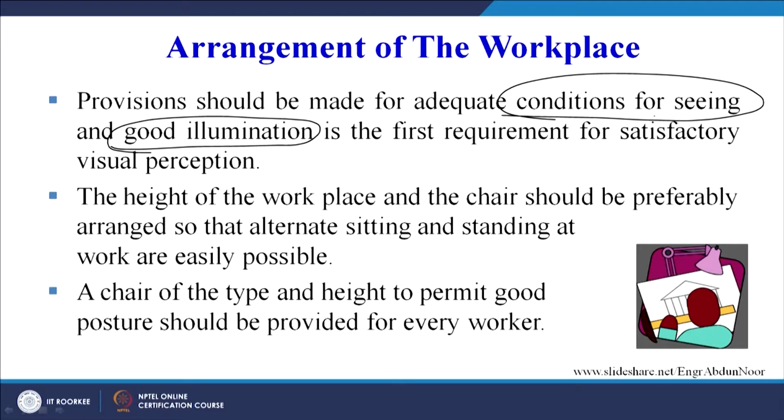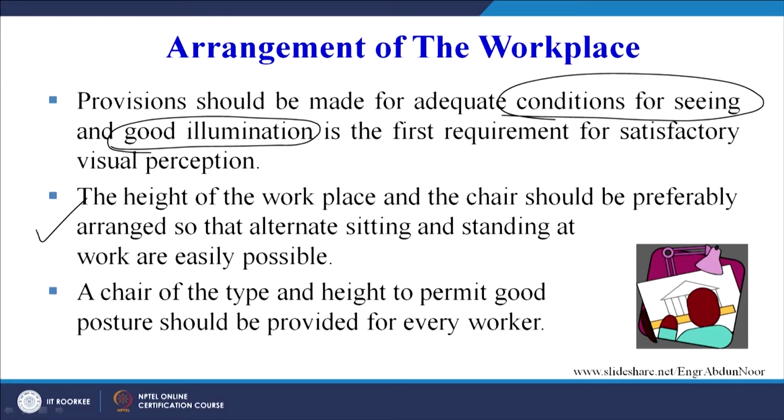The height of the workplace and the chair should be preferably arranged so that alternate sitting and standing at work are easily possible. So we can provide such a situation, the table and chair arrangement in such a way that if the worker feels that he is tired of sitting, he can stand up and perform his work, and maybe after some time if he again feels like sitting, so he can sit and start his work. So that kind of flexibility can be designed into the workplace so that the worker feels comfortable. A chair of the type and height to permit good posture should be provided for every worker. So this is related to the ergonomic design of the chair which is to be given to the worker.